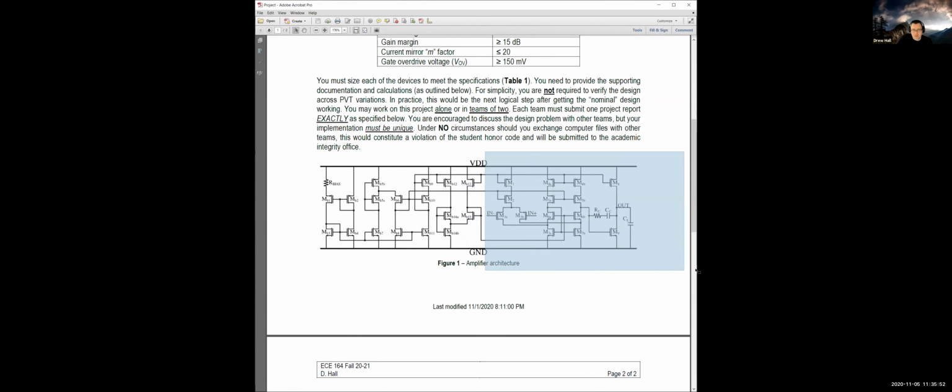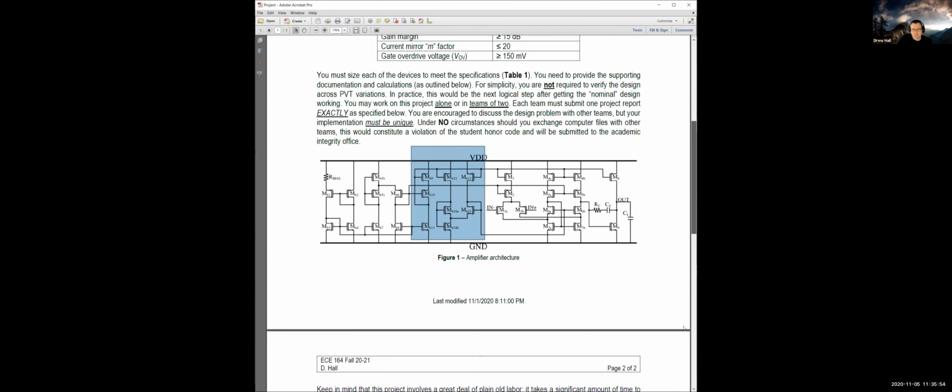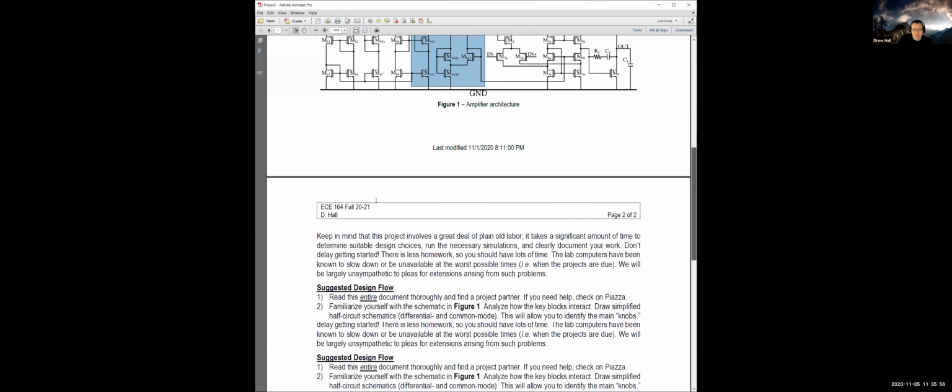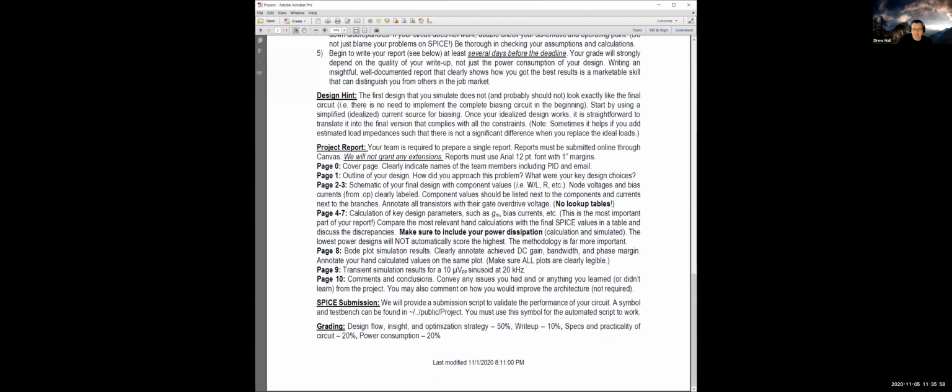Put this on 1 page, this on the other page, and make sure that you clearly annotate things like the size, the resistance, the voltage, and the bias currents, okay? There is something posted in the CAD section of the wiki of how to change the annotations. This can be quite useful to get things annotated on the design that you want.